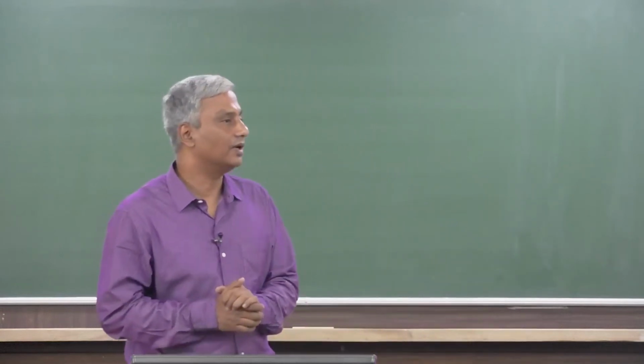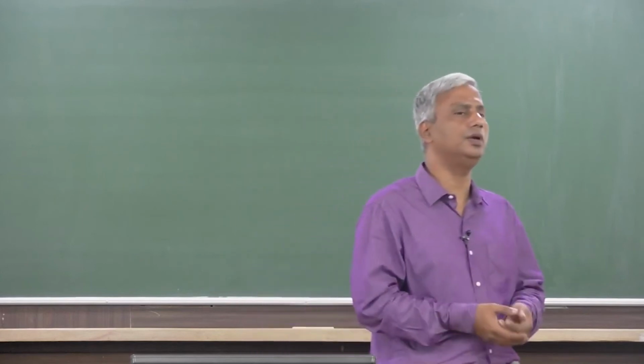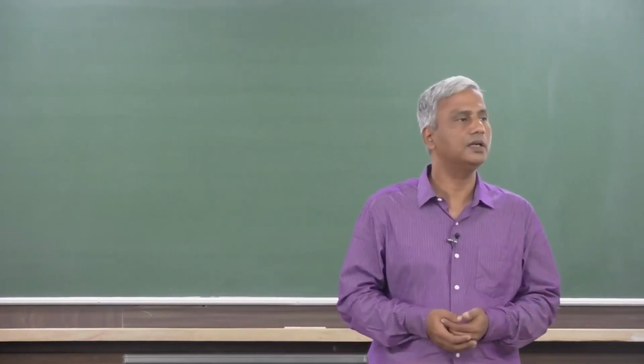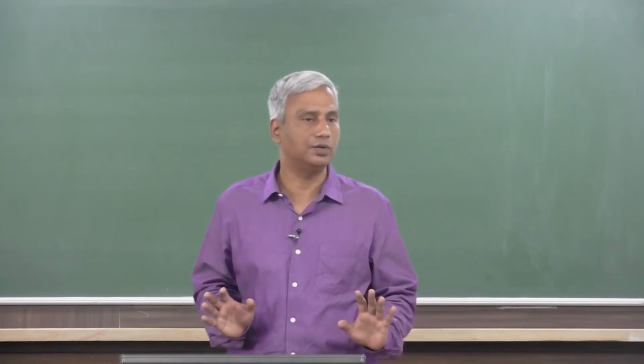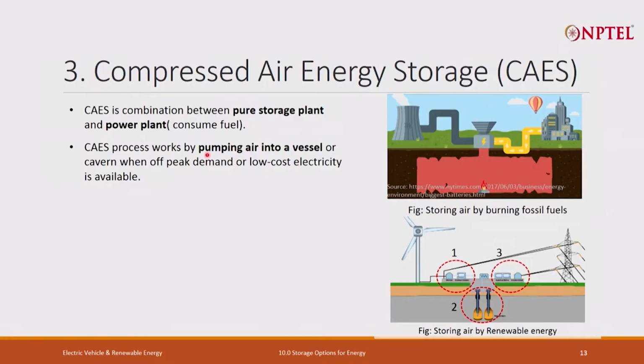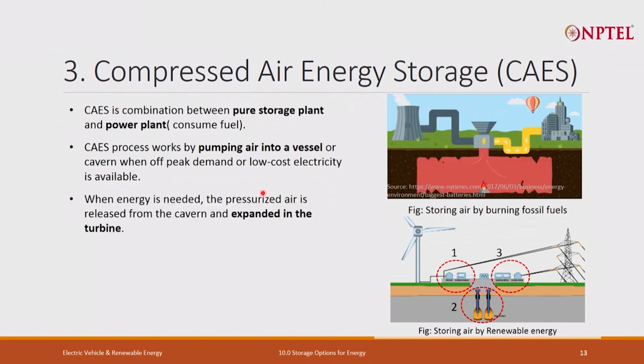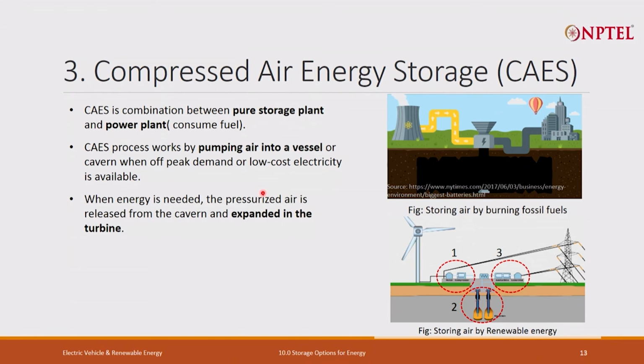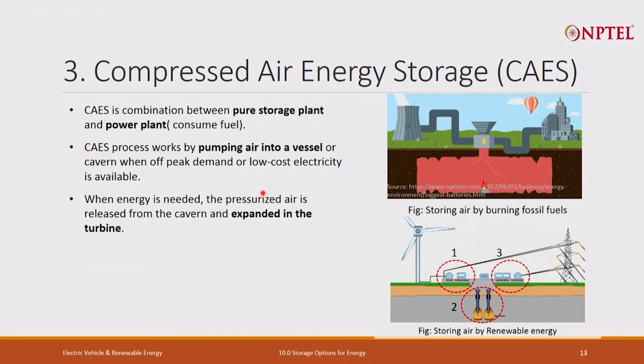But when we are talking about renewable energy, we do have a lot of renewable energy. We don't need to use a power plant, in fact. So in such cases, it would act as an energy storage only. It works by pumping air into a vessel or any cavity which is sealed off, and gives back energy to you whenever you require it by taking that compressed air from that place. It is considered to be a very low cost energy storage. Whenever you require energy, you expand it through a turbine and get back the energy.